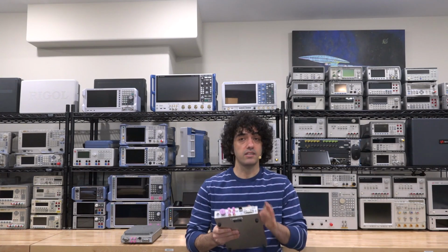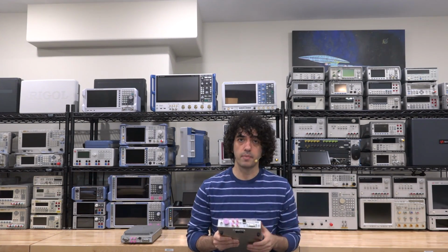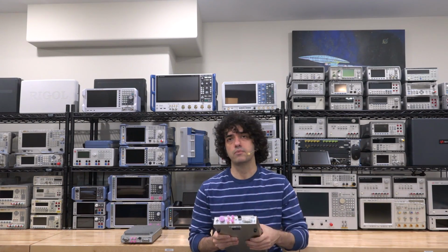but of course many more pre-selector filters and conversion stages, but it doesn't sacrifice the speed of the instrument. It still has the Ethernet interface with 160 megahertz of continuous streaming through the entire band. But it also has another trick which I'm really excited about. Now, because at millimeter wave frequencies above 20 gigahertz, you generally have higher bandwidths that you need to work with, and that's the whole point of being at those frequencies.